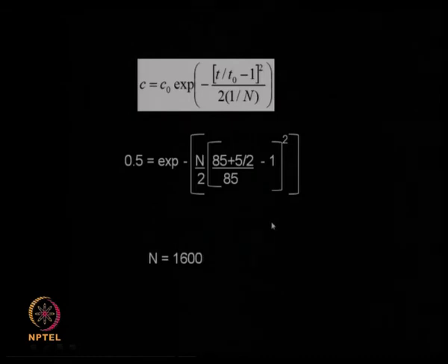So you see we did two problems, both calculating the number of theoretical stages, both based on a simple experimental procedure. You inject your solute at time equal to 0 and see when the solute is coming out or eluting out, so you know the time.